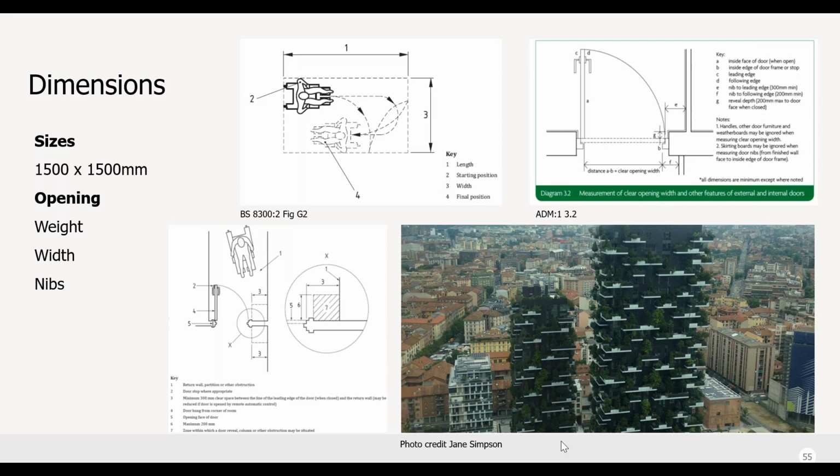The doors themselves should be treated in terms of width as you would do for any door. And note, this can vary for different locations, as I mentioned earlier, particularly Sport England. So please check the relevant guidance. One area that is important to get right is the clear leading and following edges. This standard requires 300 mm on the pull side and the door to be located no deeper than within a 200 mm recess.